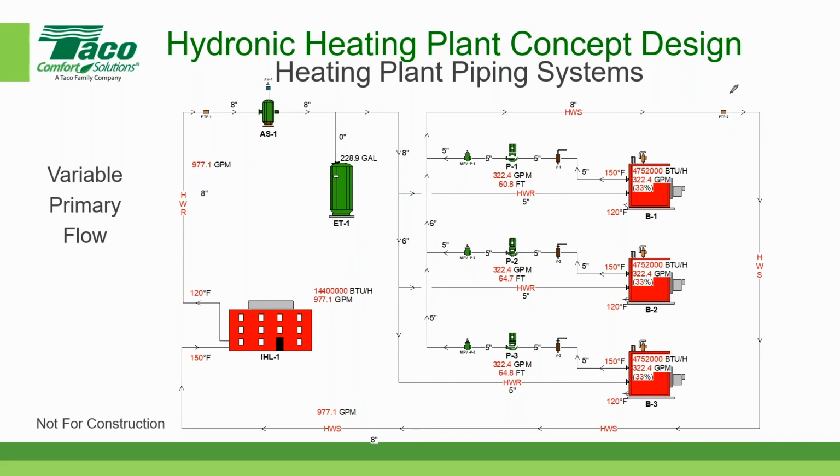Well, there are advantages. There could potentially be advantages from a hydronic perspective, but if it's a low-rise building, which is the one we're talking about today, I like to consolidate all of the hydronic heating plant equipment in one location. I like to have everything in there, and the only thing leaving that central location would be the distribution piping to the terminal units, and we just outlined those terminal units. Perhaps they're fan coils, baseboard radiation, panel radiators, radiant floor, radiant ceiling, air handling units, that sort of thing. So I like to consolidate everything into one location. There could potentially be a benefit, but I think in general, it's nice to have everything in one location.